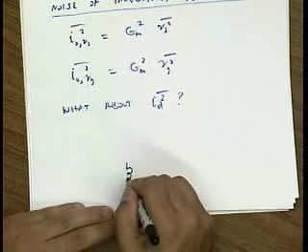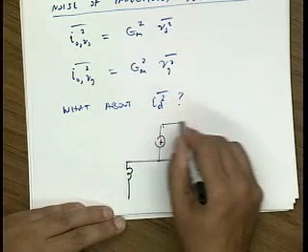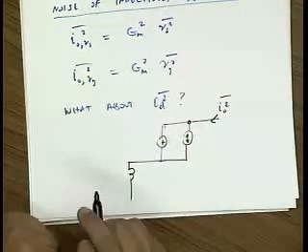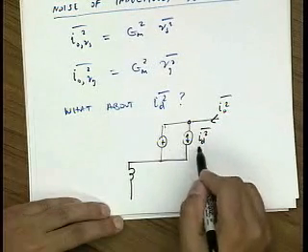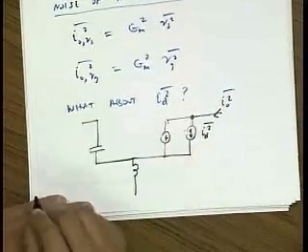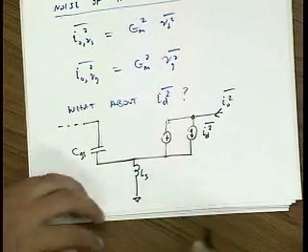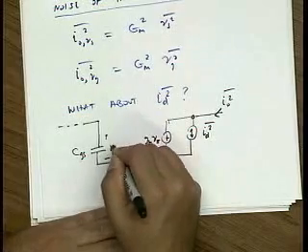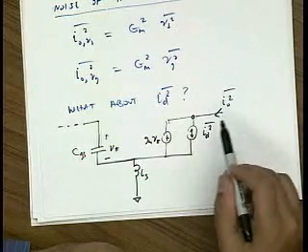So let's draw a picture here of what's happening. If I look at this current, and I'm just concerned with this current source, the drain noise, then by superposition, of course, I can set all the other noises to 0 and just focus on this noise source. So this is CGS. This is LS. Now it seems like this noise source just flows straight into the output, just like a common source device.